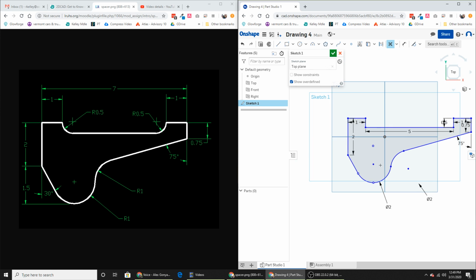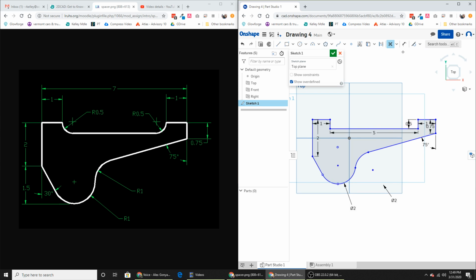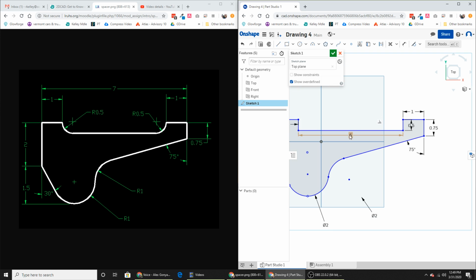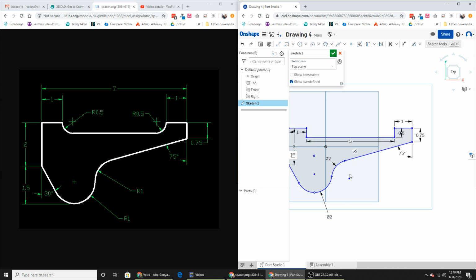All right, looking around, this looks pretty good. I'm going to turn off trim. I'm just going to move some of these dimensions around to clean this up. This one's going to be in the way because I'm about to do a fillet here. And this one is now pointing at a non-existent part of the circle. Can we move this somewhere? Yeah, how about right there?